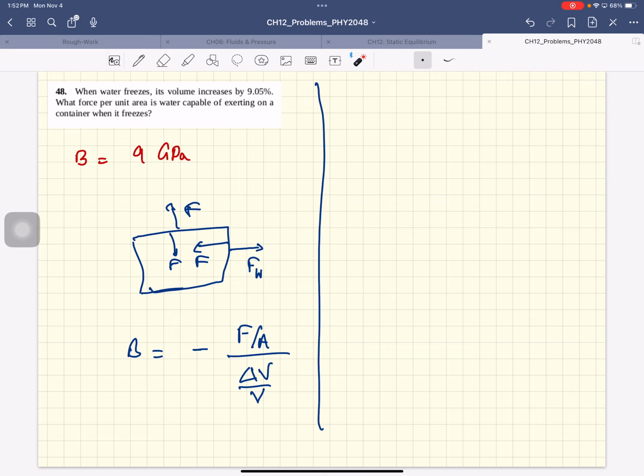So Young's modulus is mg over, and it's a circular cross section, pi r square. So this is in the denominator, we'll leave the pi there, we'll bring the r square over there. So r square is mg over pi